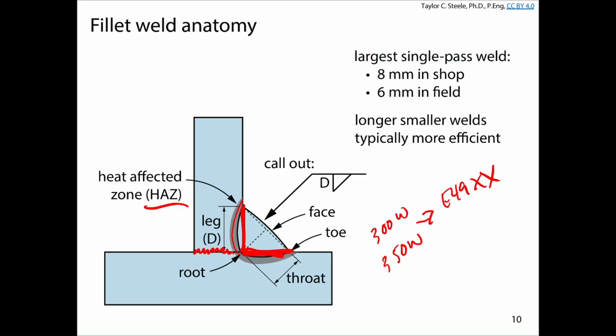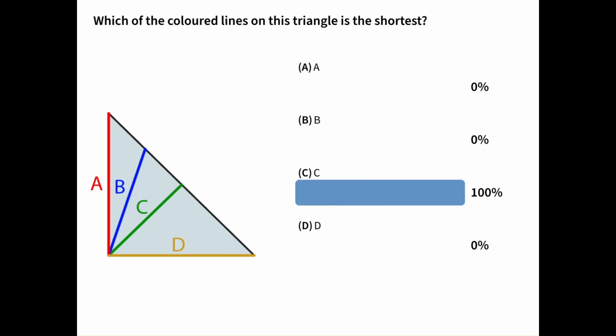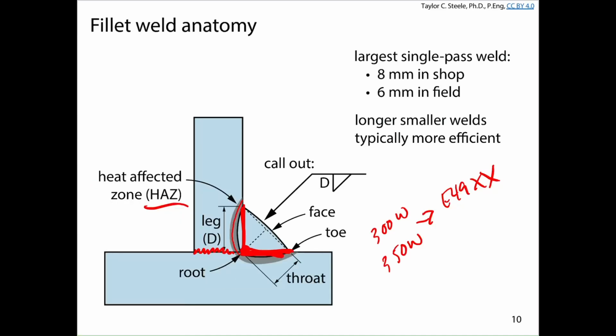When we're looking at the potential failure of these welds, as I'll show you in a minute, we're going to be focusing on what we call the effective throat of the weld. The effective throat is basically, like we had on the pull everywhere slide, dimension C. That's the dimension from the root of the weld out to the face perpendicularly. That's the shortest distance. And we're going to see, as the stress gets transferred from this leg of the weld to this leg of the weld, those stresses have to pass through in shear or tension through the location where the stresses are going to be the highest.